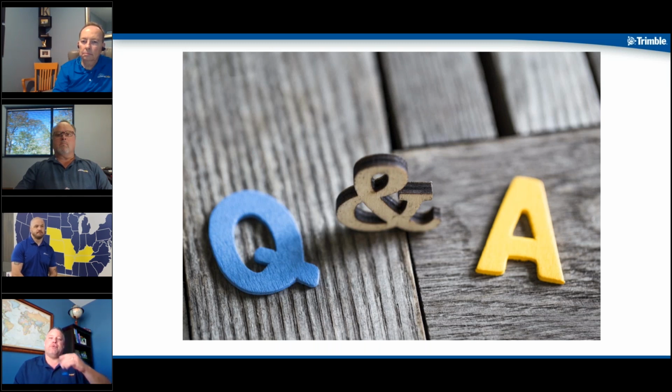That height could be 5 stories, that height could be 40 stories, but at a certain position up, the building's going to move quite a bit and sway too much, and then you're going to introduce error into the project if you're using control points off the building. But if you're 1, 2, 3, 4 stories up, I wouldn't hesitate to use any type of reflective prism or reflective tape on other buildings as control points.